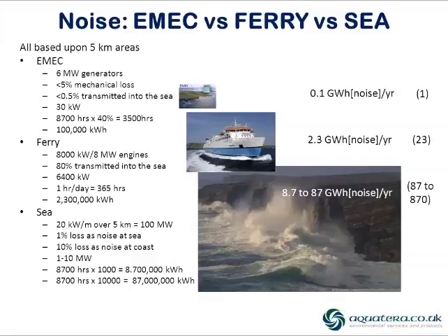And you can see the way we've built this up. We've started with a number of generators. We've looked at the mechanical loss. We've then looked at the transmitted noise loss into the sea and looked at the energy conversion of that. And then we've multiplied that amount of energy by the number of hours that the device is in the water, and in this case the capacity factor as a surrogate for the efficiency or the power output of the device.